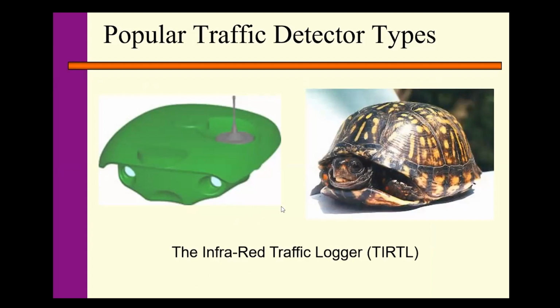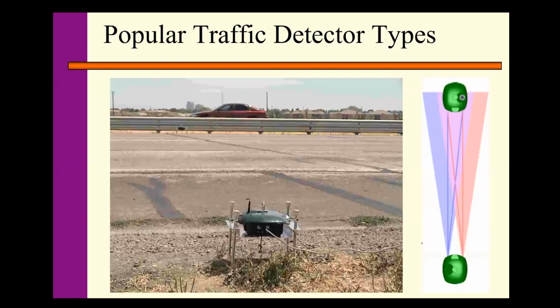We pair those traffic sensors together on the roadside. When one of the sensors sends out the beam and it is received by another sensor, when a large truck travels on the road, you see the axles can be counted when the vehicle cuts the beam.